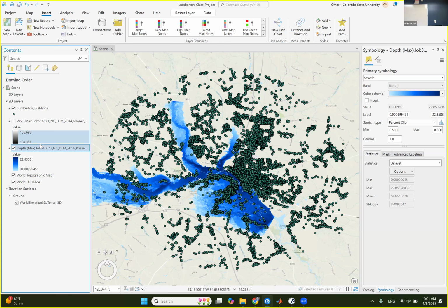10%, like what? 20,000, 10% is going to be 2,000. That's a really good guess. So around 1,800 to 1,900 of the buildings got flooded. When we run the damage analysis, it doesn't make sense, or it's a lot of work, to give the MATLAB code lots of buildings that have zero flood depths, because if a building has zero flood depth, the damage is going to be zero. So what I would do is extract only the buildings that got flooded, that 10% of the buildings. Why? Because I want to save time, especially if I have 500,000 buildings, that's going to save a lot of time. MATLAB is not going to take that much time.